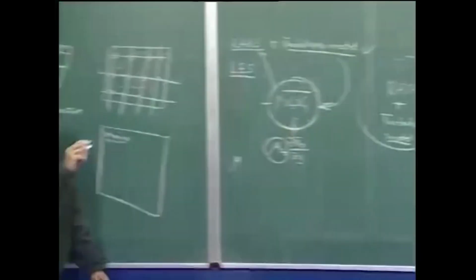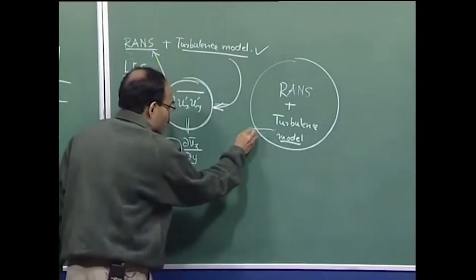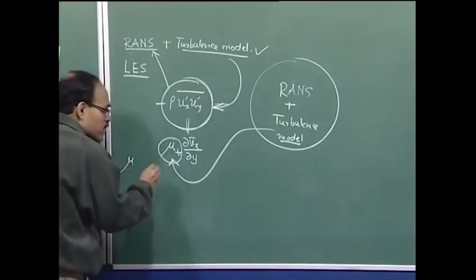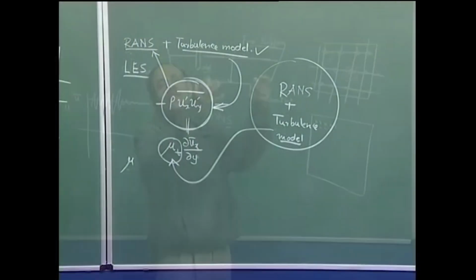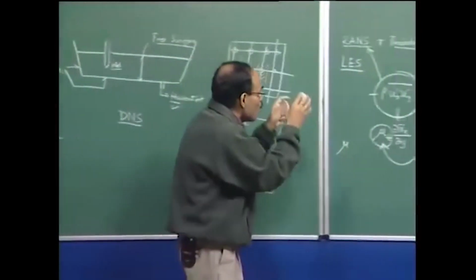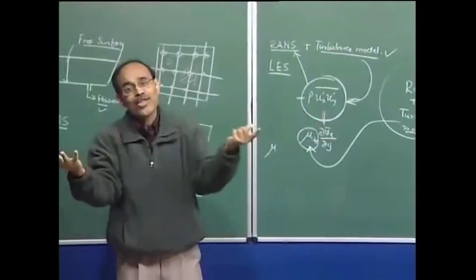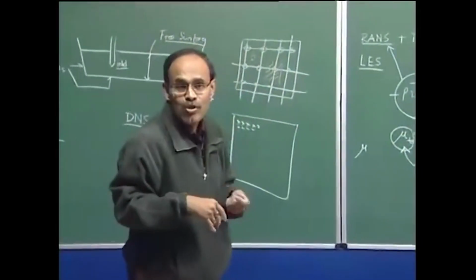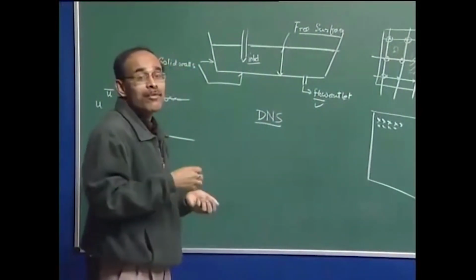So, going to the root of the problem, what does the turbulence model do? The turbulence model provides us the distribution of mu t in the domain through an appropriate mathematical framework. We obtain mu t from the turbulence model and substitute it into the RANS equation, then the RANS equation boils down to 4 equations, 4 unknowns, and we are in a position to solve and meaningfully obtain the velocity field prevalent in steel making.